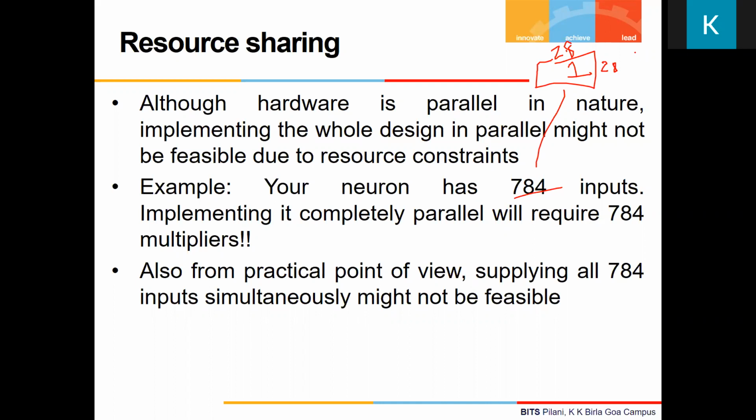The second one is, if you use an adder which can add 784 numbers in parallel, that will be a super huge combinational circuit. Your Fmax will be impacted, so the frequency at which your circuit will run will be very low, which is a bad thing. Maybe to overcome that, you will add pipelines there. Again, resource utilization will go up. So not a good idea.